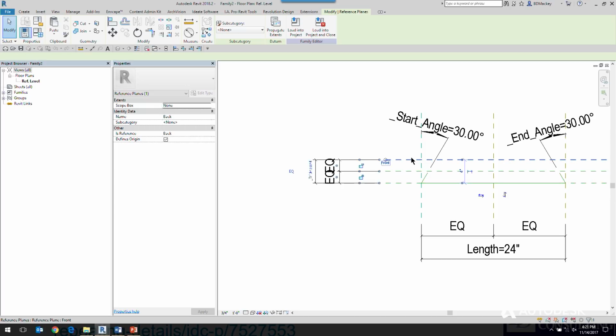The other thing is, if anybody follows my blog, I actually realize, who here names the reference planes? Anyone? Somebody else notice that new feature in 2018? If you use the dimension command or the align command, it will see the names of your reference planes in your families. Sorry, that was a new feature that my type A personality was cheering for. Yay, for the last 12 years, it's paying off.